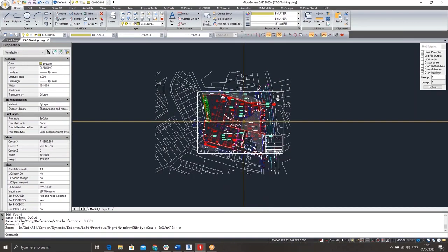Okay, so the fact that we did Z, enter, E, enter, zoom extents, and it brought us that far back out means there are entities within this drawing now that are further away than others. So that's an important note to make as well. We don't want that to happen before we bring our CAD file into our field software, because especially with our field software, we'll try to present a zoom extents upon first import of any reference file.